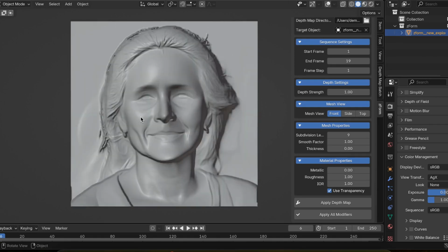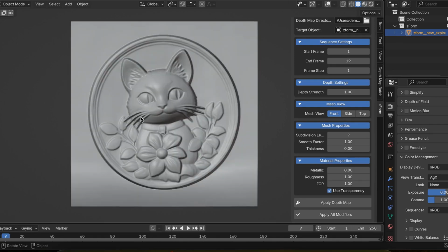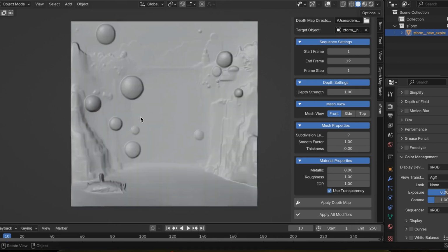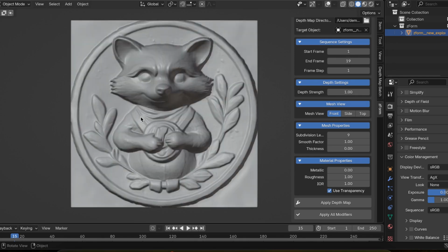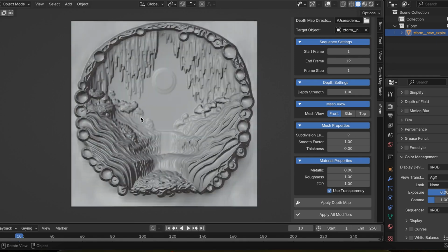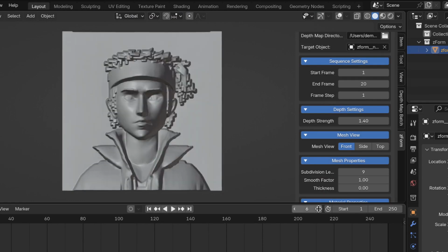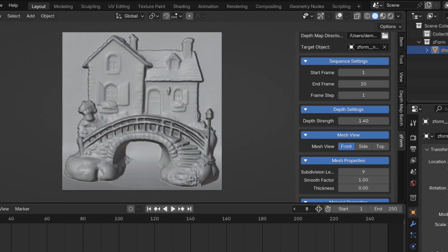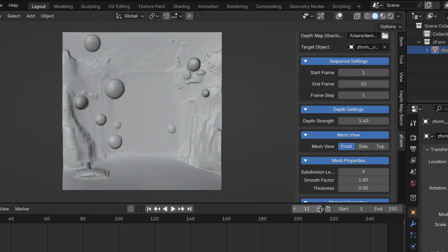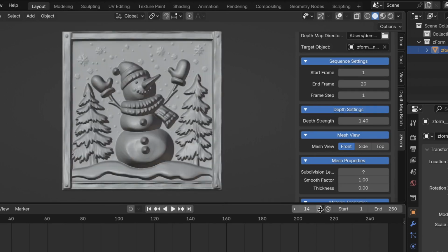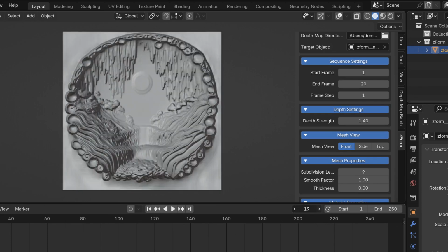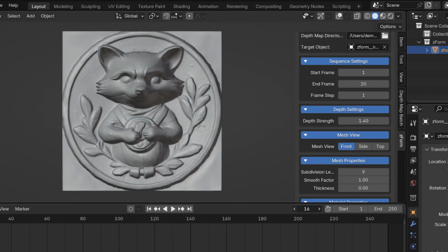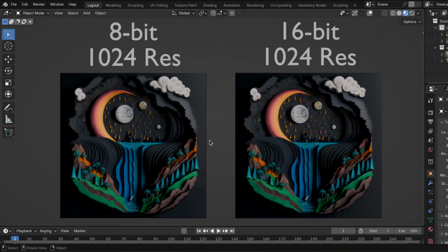For the examples today, I'm using the directory option in the top right, and I'm opening up the directory where it has all the images, and then referencing the depth maps for those images. The way this works, it will transform all of your images to 3D mesh for the entire directory. You can change and view different images in the directory for the 3D mesh. It's leveraging Blender's timeline. In the first frame, that will be the first image, and then if you go to the right for the second frame, that will display the second image, and so on. You can just keep scrolling in the timeline to see every single image that you had in your directory converted to a 3D mesh. Alright, that's all I got.